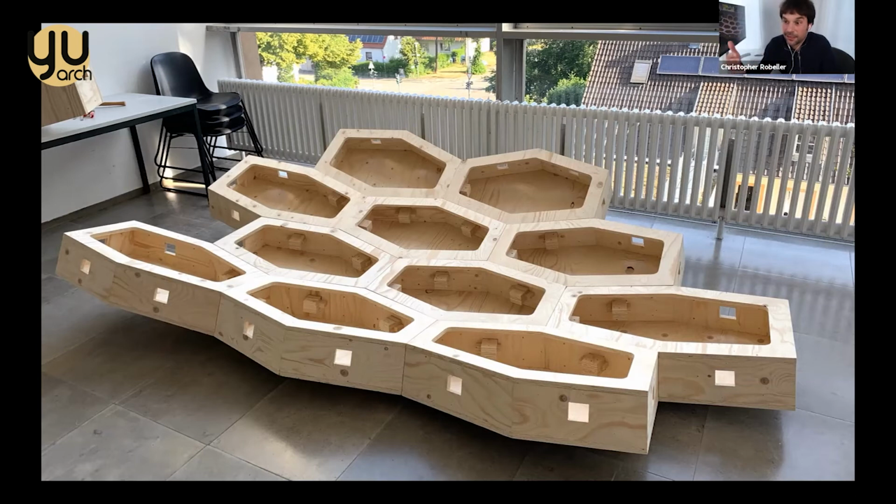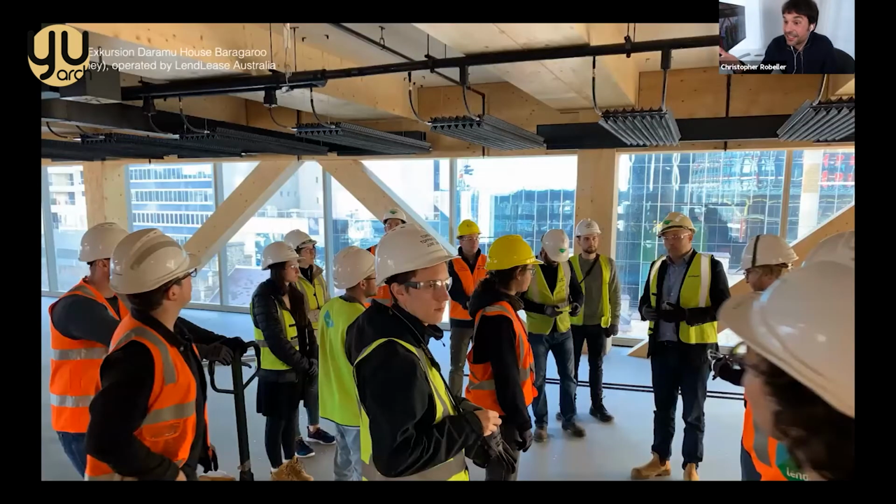But luckily, the larger you make things, the easier it gets, because the tolerance is the same and the structure is larger, so it's less problematic, which is a shame because it's so difficult to make models of these things. And it did work out with the precision after much calibration of the robot. If you see a robot in a university, you know you have to calibrate it because it has been abused and crashed. Before you want to do anything with a robot, you need to calibrate it, and then it's going to give you good results.